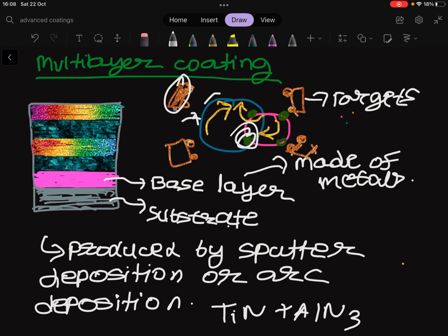Titanium aluminum nitride films, where the aluminum to titanium ratio is around 2:1, exhibit enhanced hardness values when annealed at high temperature, around 800 to 1000 degrees Celsius, due to the formation of coherent precipitates, which are cubic titanium nitride and aluminum nitride, which provide an additional obstacle for dislocation movement. Addition of aluminum to the coating is to increase the high temperature oxidation resistance of our coating.